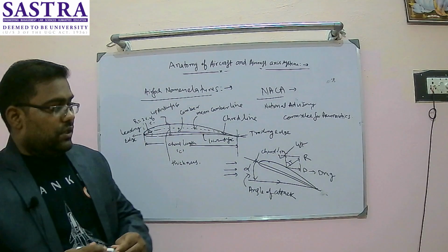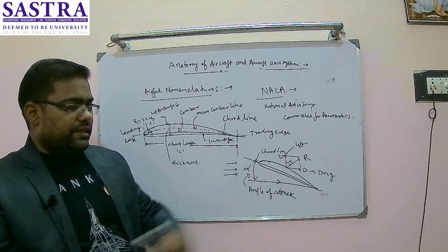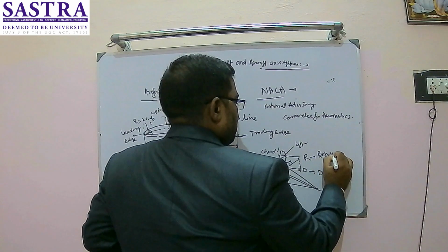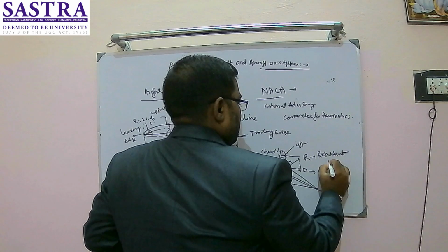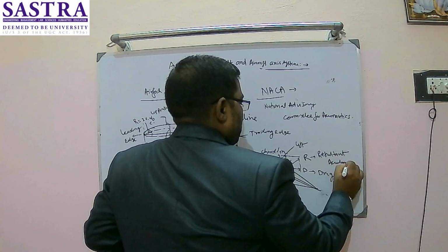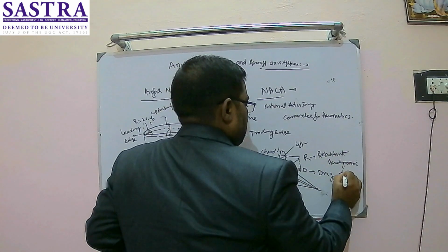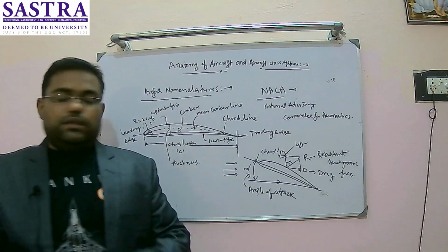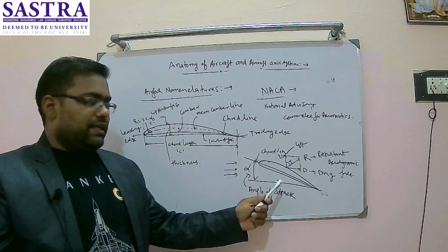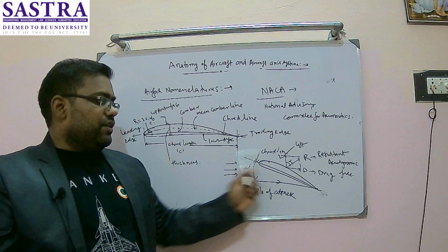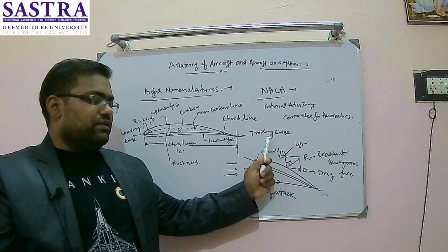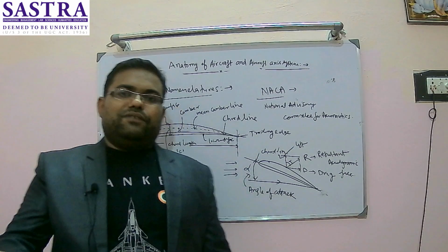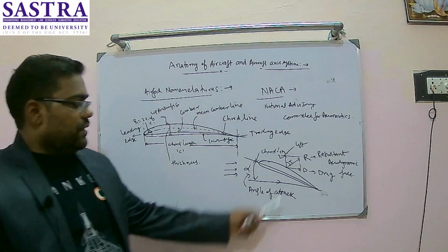Right, angle of attack. This is the resultant aerodynamic force. The component of the resultant aerodynamic force perpendicular to the free stream direction, this one component we are getting, is known as lift, and this lift will support your weight. The moment it is more than weight, your aircraft will be fully airborne.